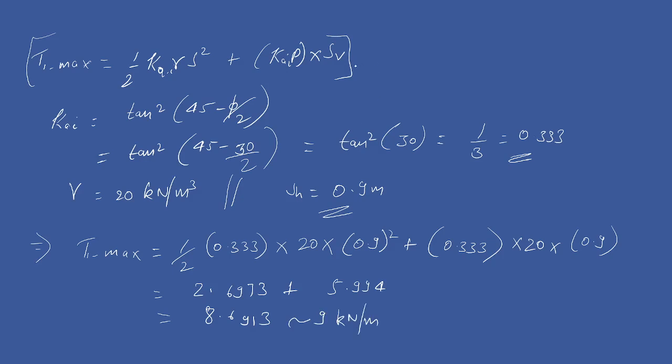So yeah, I was talking about how we got this formula. Let me discuss this. This is your wall, and these are your reinforcements. First of all, you need to calculate the tensile force in this reinforcement. This reinforcement will basically be resisting the whole lateral pressure coming from this soil plus half of this. This depth is given as 0.6 and this depth is 0.3 meter, right?